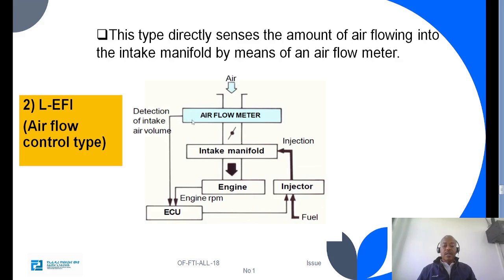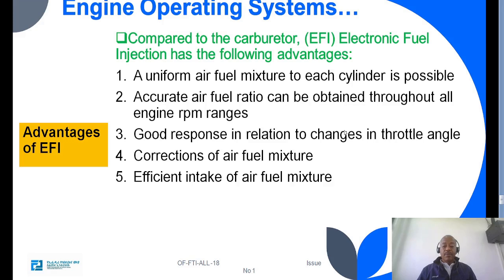Then the signal is sent to the ECU. ECU also receives the engine revolution data and gives a command to the injector to inject the required and appropriate amount of fuel.